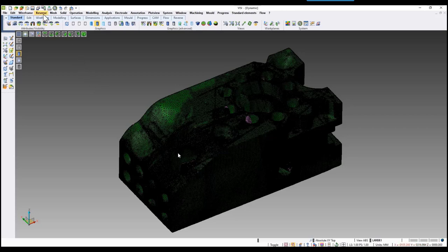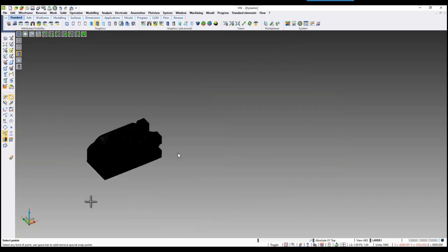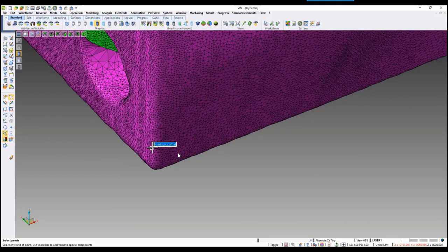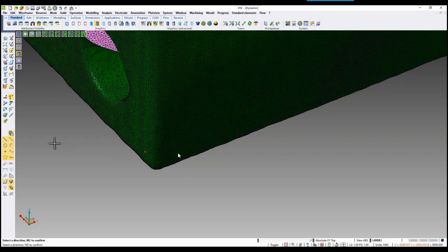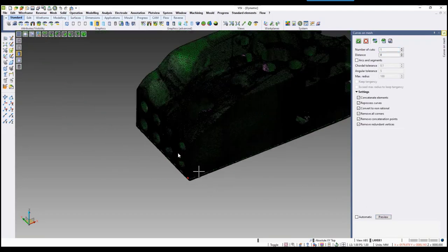So again, a quick video of this. We can go into the curve on mesh option, select our mesh, and pinpoint and click different points for where we want that section to be based. So we pick, let's say, our point, we choose the direction we want it to be associated to, and when we hit preview, it creates a section. That section can be turned into a profile, it can be turned into arcs, and so on, to be able to extrude and create that into a solid.